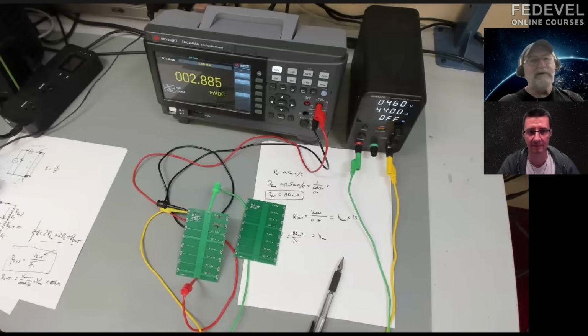Designing that power distribution for the 100 to 500 amp devices is a challenge all by itself. It's not about signal integrity, it's about life at DC, and that has its own set of challenges. And it's these kinds of experiments that we did here that help feed your intuition a little bit, to give you confidence in the simple approximations and quick estimates, have a rough idea of what's going to be required or where the problems are, and then you apply the 3D simulation tools to help design those virtual prototypes.